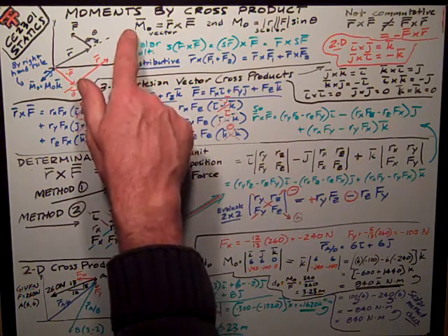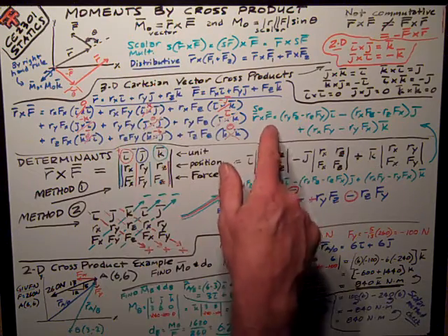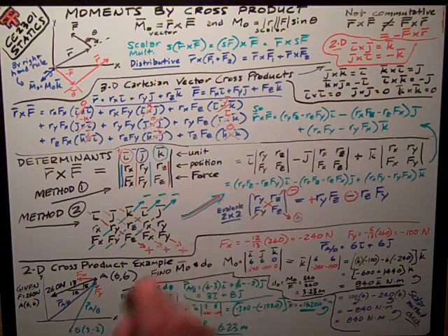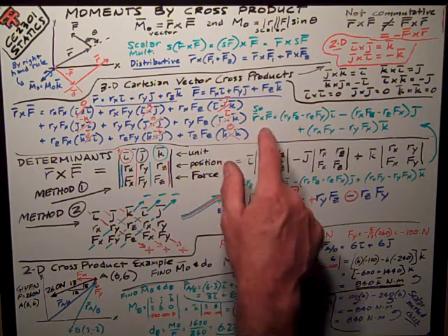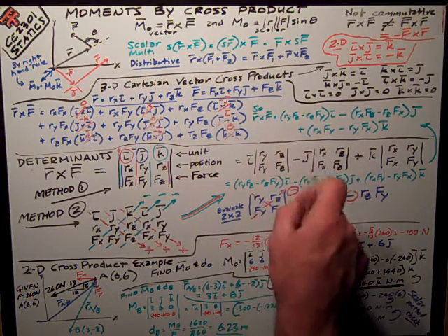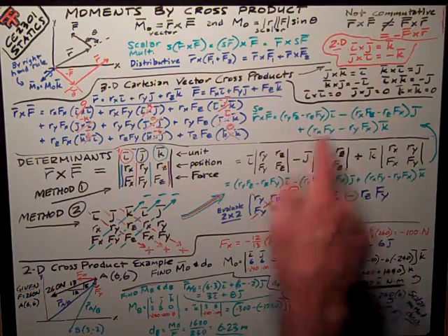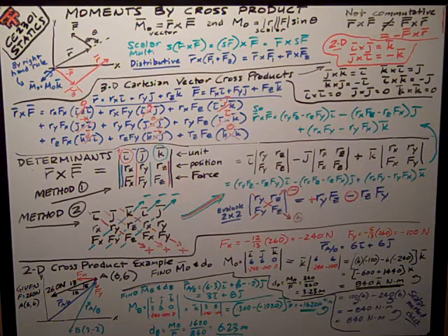The moment about any point is the position vector crossed with f. I just multiply those terms together, and I get a scalar. So this moment is also a vector in 3 dimensions too. So it's just these Cartesian components of the vector, Mo.